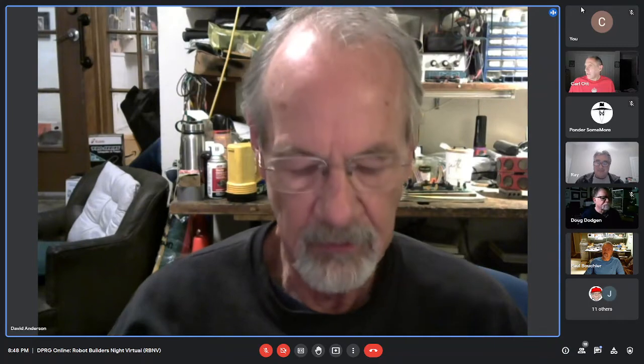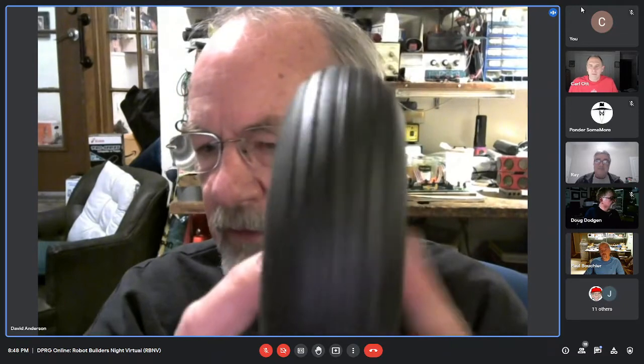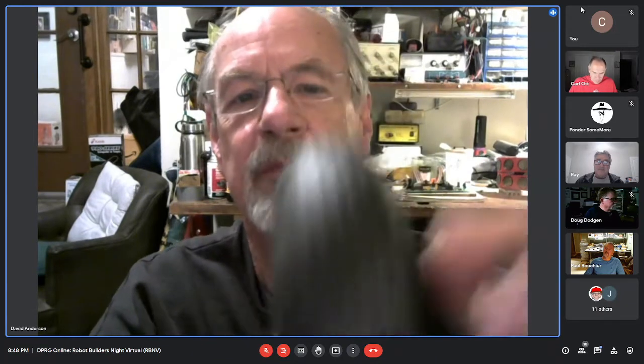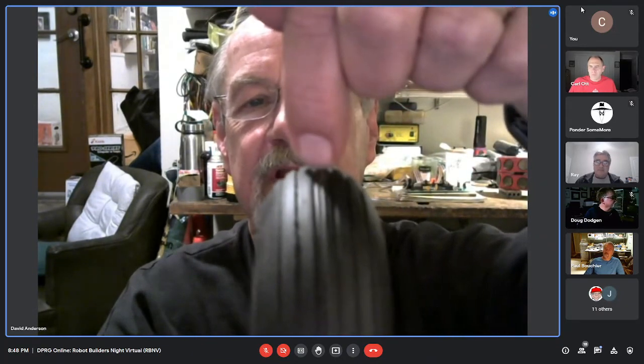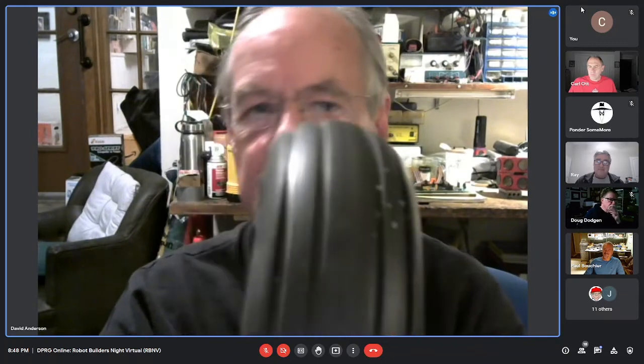I had one point to make regarding Paul's question about skinny tires being better for odometry. My only caveat is that skinny tires are problematic for outdoor robots because what you want is traction. What I've found, and let me hold this up, is a wheel with an oval profile. So as far as odometry is concerned, it is a skinny tire. And here's a big one. At one time I was going to build a big balancing robot, and these were the wheels. It's the same thing.